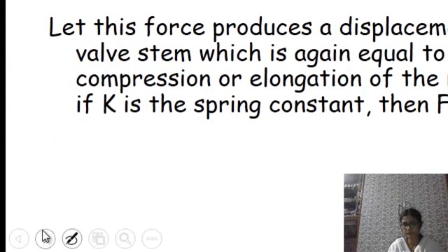Now, functioning of the pneumatic controller: the diaphragm is generally made of neoprene rubber or metallic wire reinforced neoprene rubber supported by a backing plate at the center. The air pressure acting on the diaphragm is the controller output, that is (M − M0) × A. A is the diaphragm cross-sectional area, where M0 is the control action signal at zero stroke condition, that means when there is no action, and M is the control action signal.